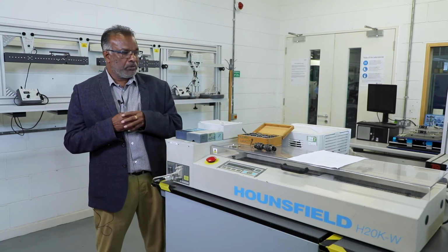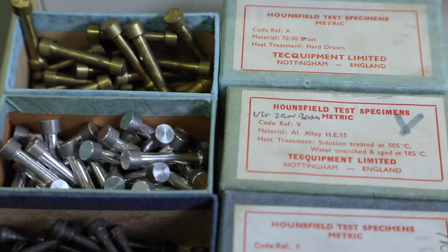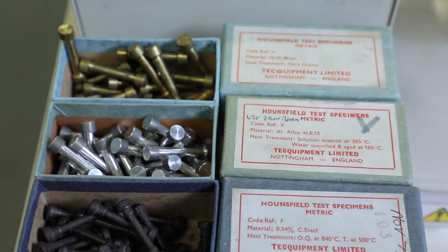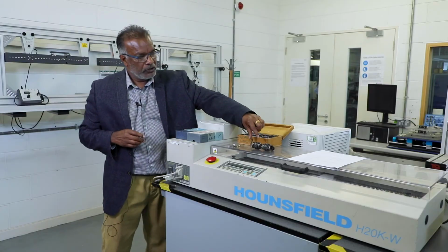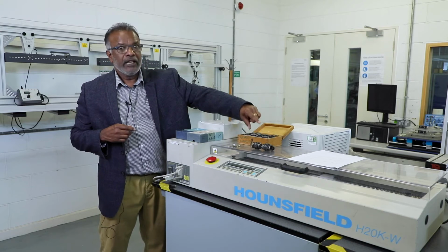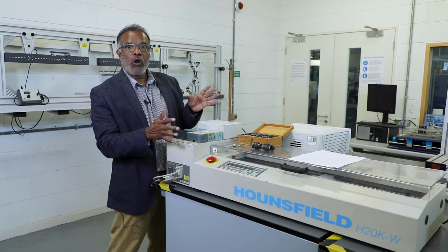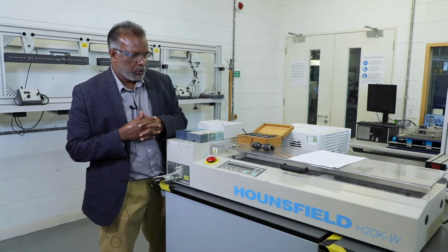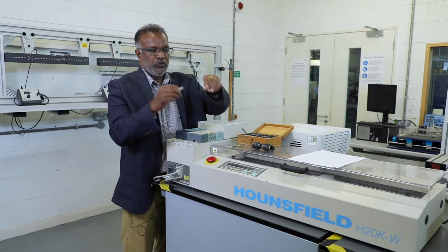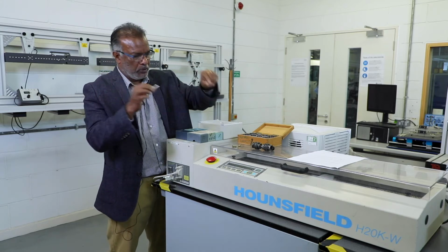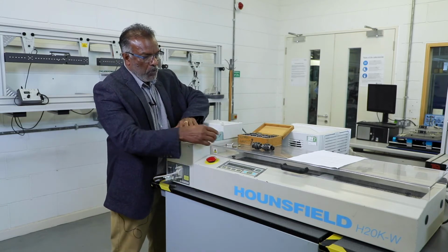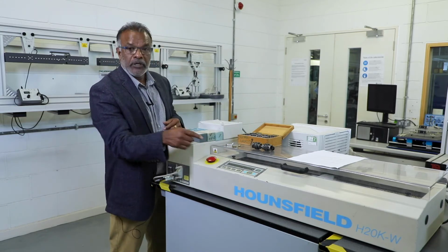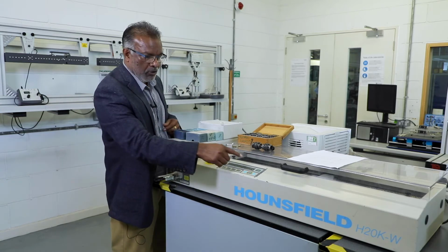The test is very simple. Specimens will be taken and then clamped into these 2 collars, as you can see from here, and then a load will be applied uniformly until the fracture takes place. And this is the sample of the fractured specimens. And the corresponding behavior of the materials will be displayed over here.